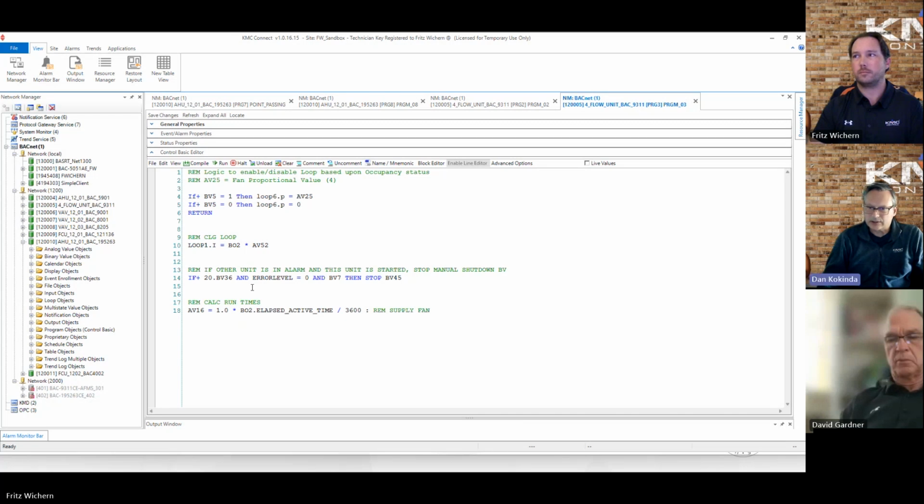So, read run times, depending on how many devices you're reading. That's a good question about staggering run read times. Fritz, do you have... I've got to think about that for a second. About Kevin's question: stagger the read run times in NetPoint, depending on how many devices. I will look that up. I have read that, and I think you want to limit it. You don't want to just go crazy with it, and you don't want everything set to the same value, because you'll end up being bursty, is how I've heard it described with your communication. But we can double check on that.